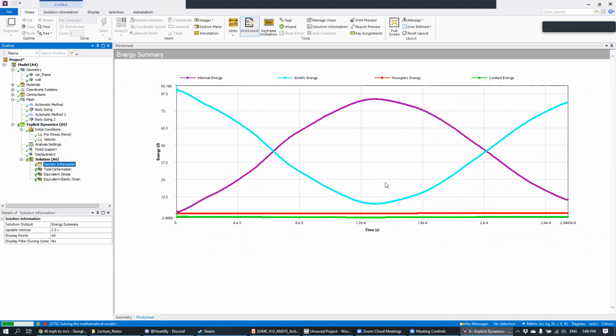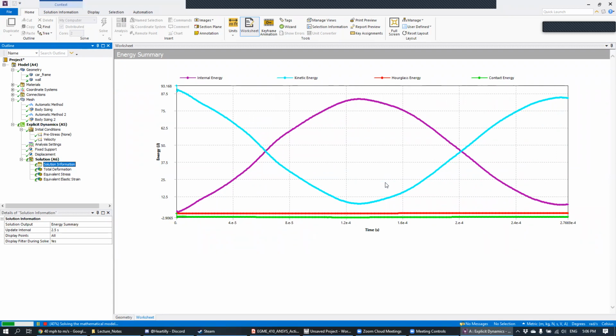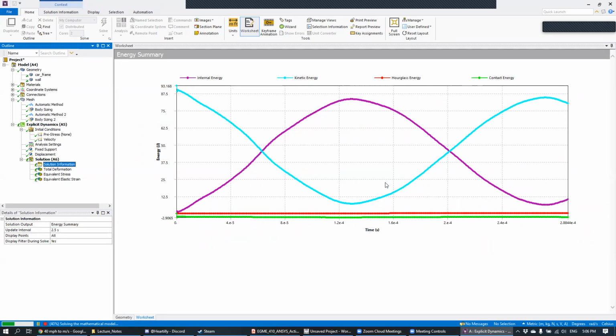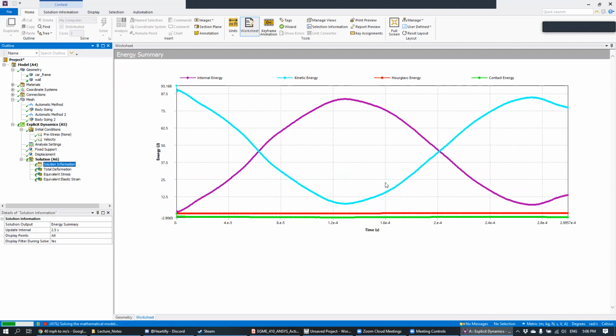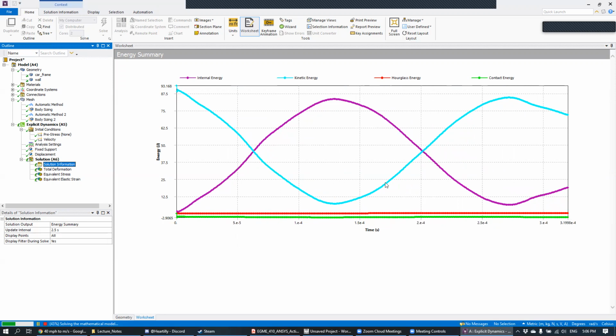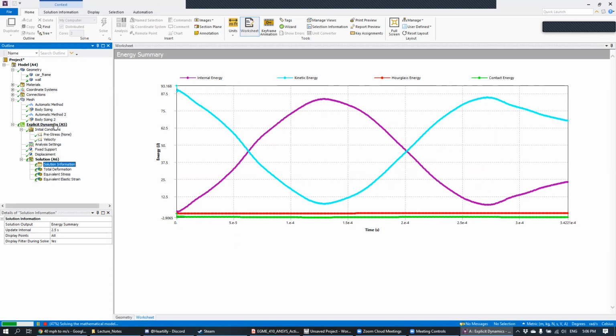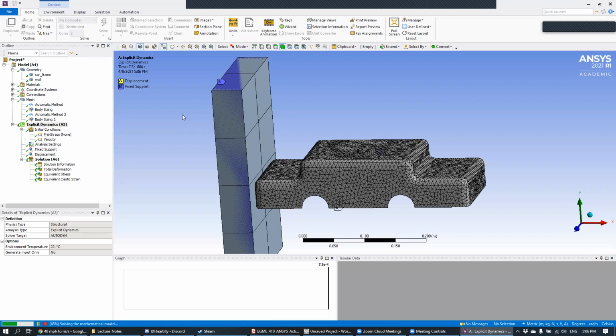It's been a while since I've used SolidWorks, so I'm not sure how you would actually cut the part in half, but it happens all the time in engineering, because you have symmetrical parts all the time. I imagine there's some functionality in there to cut it in half. Once you do, throwing it into Ansys is simple, because there are built-in symmetry boundary conditions. After this finishes, I'll show you the symmetry boundary condition.